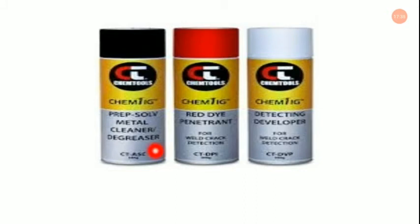So, first is your cleaner, then your red dye penetrant, next is your developer. These are the solutions you need to apply to perform the dye penetration test to detect weld cracks.